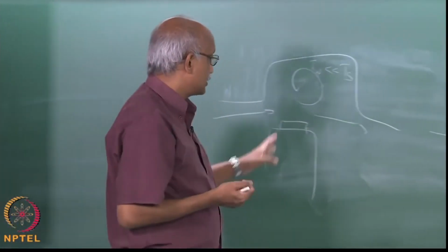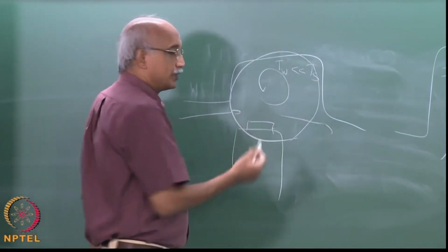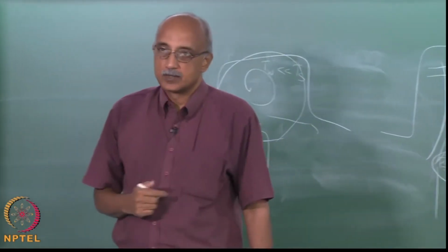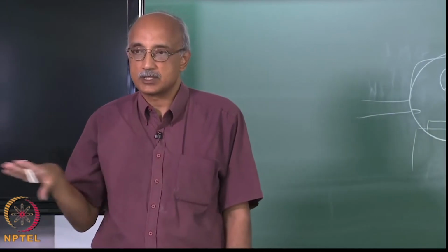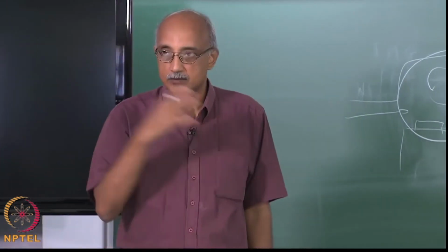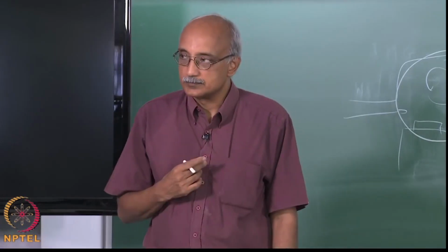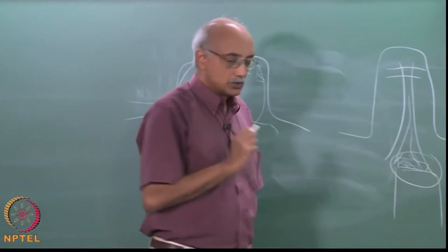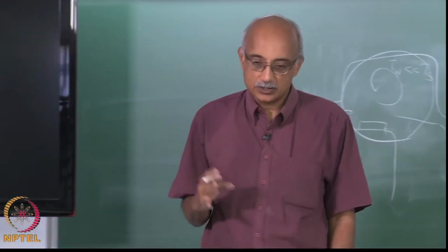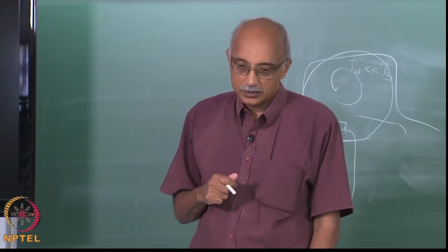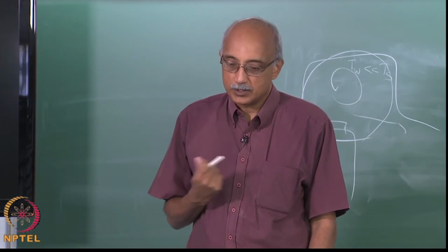If you are trying to do this in a horizontal flow reactor, then you really have to do a CFD model over the entire reactor, and you have to control not only what happens in the vicinity of the substrate, but essentially everywhere within the reactor. So, complexity goes up, cost goes up. All right. So, in terms of metal organic CVD, these are some of the considerations you have to keep in mind given the high reactivity of the precursors.